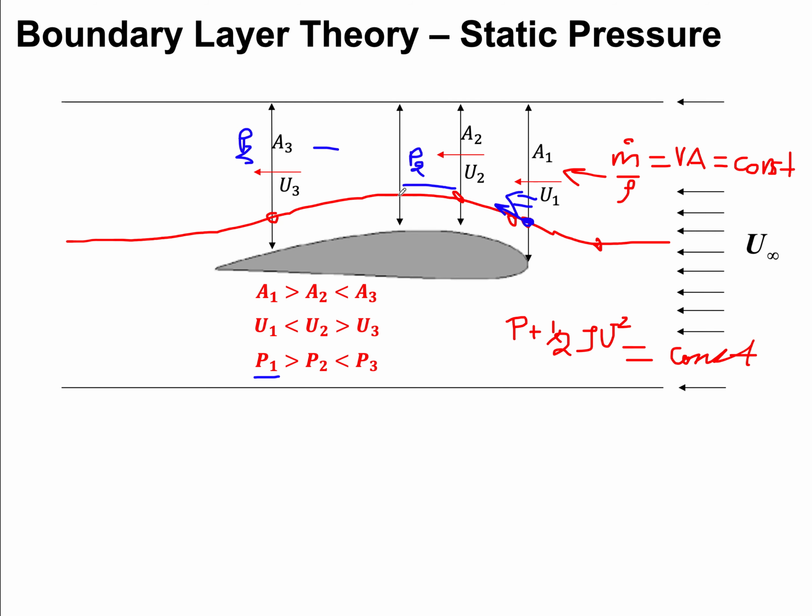As a fluid element moving along this streamline, what I will notice is that as I move forward, I encounter a region of higher and higher pressure. So the pressure is actually going to start retarding me. And this has strong implications on the boundary layer. We're still talking about boundary layer theory. Whether in this region the pressure is helping push the flow forward in the direction of the flow, or retarding the flow, trying to slow it down, has implications.